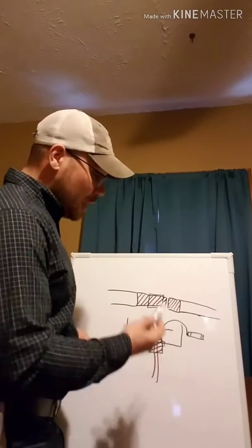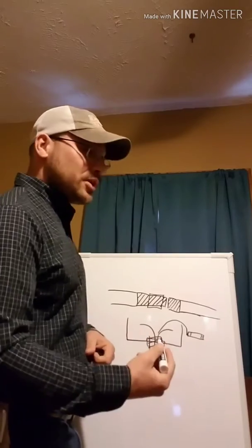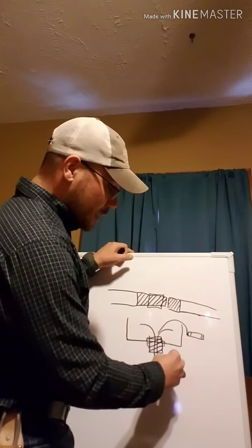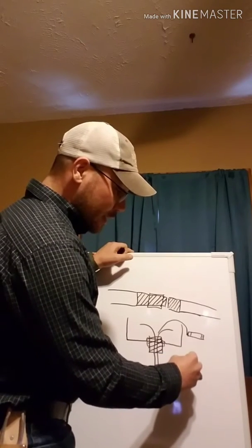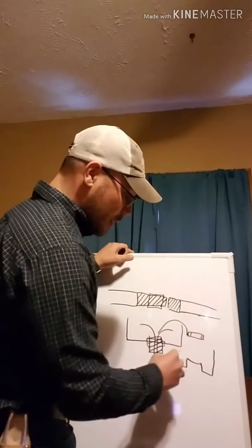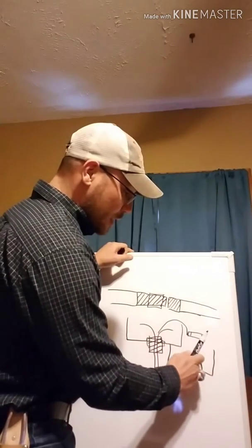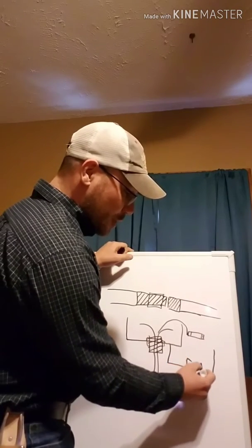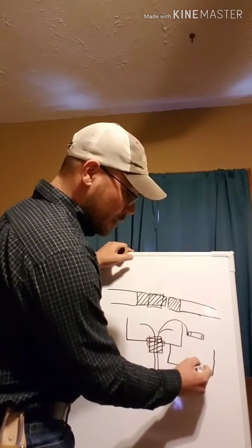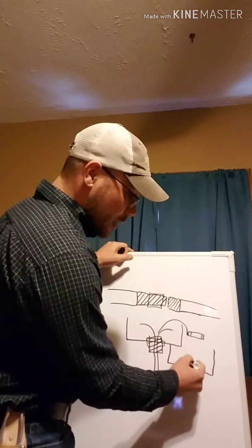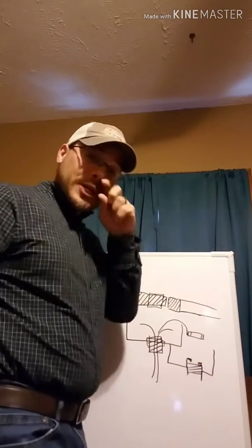Okay. Now it says unless the box itself protects from it. Sometimes you'll get a box that on the bottom side has a threaded hub here in the box, and then there's a hole right here so that when you put your conduit in, you'll actually thread your conduit in here, and then these two ends here protect the corners.